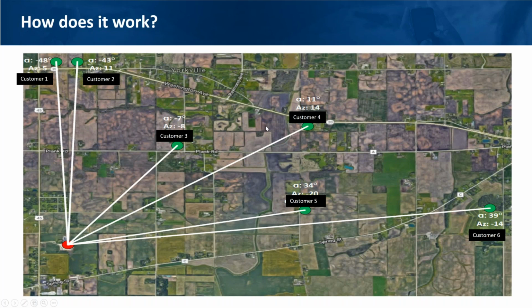Fundamentally, what we are recommending is that if you want to achieve MU-MIMO, you have to have a minimum of 10 to 30 degree azimuth delta between 2 subscribers that will be groupable, or a 50 to 70 degree delta between all of this in a 90-degree sector. So this requirement is relatively lax in our opinion. Finding a couple of subscribers that can be groupable becomes easy in a situation like we're seeing right here.